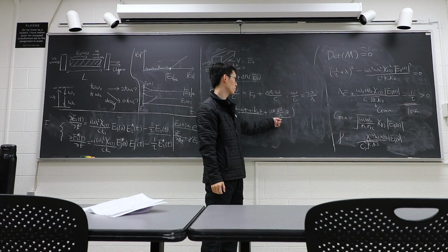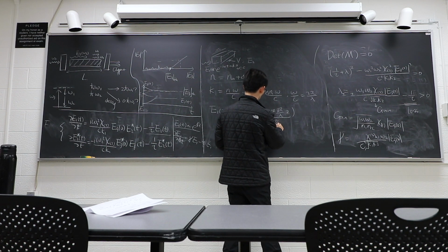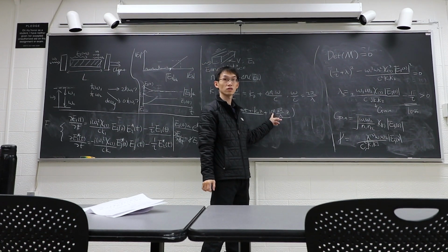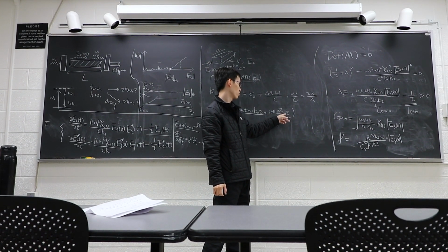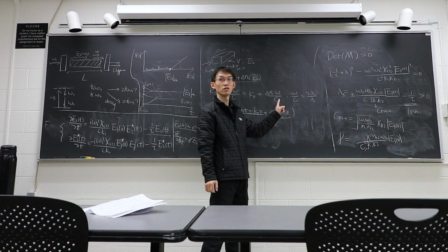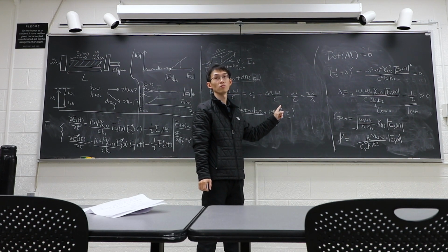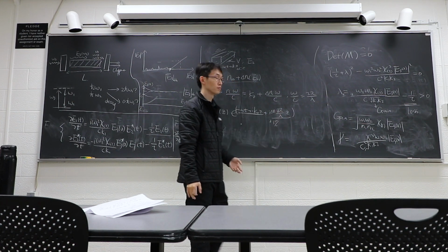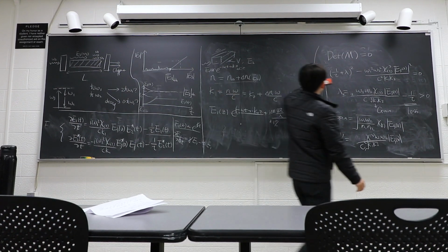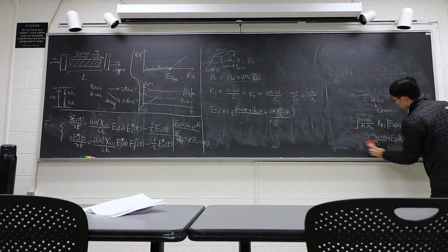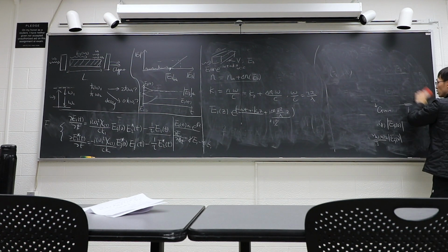And this can be quite large, because think about it. If you change 1%, usually you can't. Usually it's, I think, 0.1%. Let's say 0.1% of your refractive index, then you only need to travel 1,000 wavelengths to make it 1. And usually one wavelength is 1 micron. So if your device is 1 millimeter long, then you can already make a pi phase change. So this is the regular way of describing this effect, and it's good enough for everyday experiments.